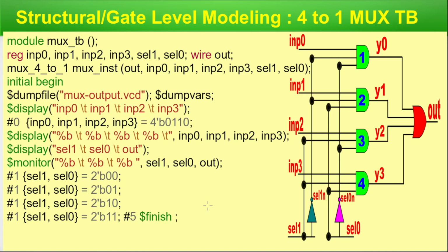As I have mentioned in previous episodes, Verilog is a transient simulation. That means we have an independent time axis, with respect to every other change, whether we change it or it changes as per the circuit operation. So the timing simulation has to have an end, and this end is defined by this finish command. It is a system defined command and a reserved keyword, and hence I have kept it in green.